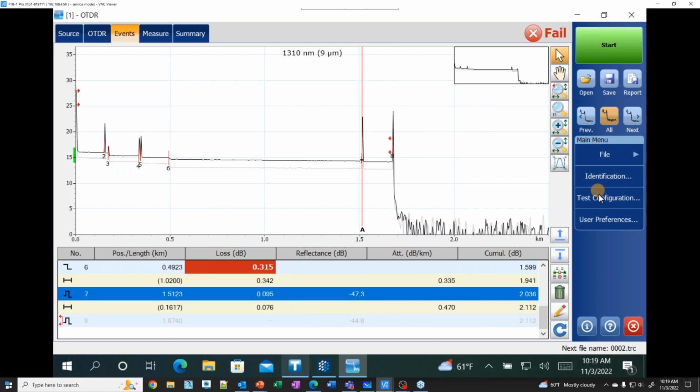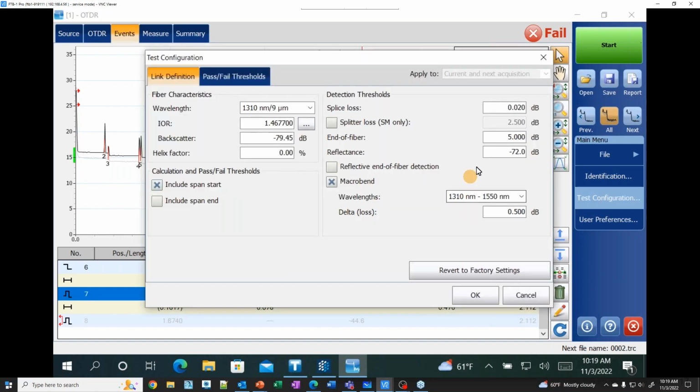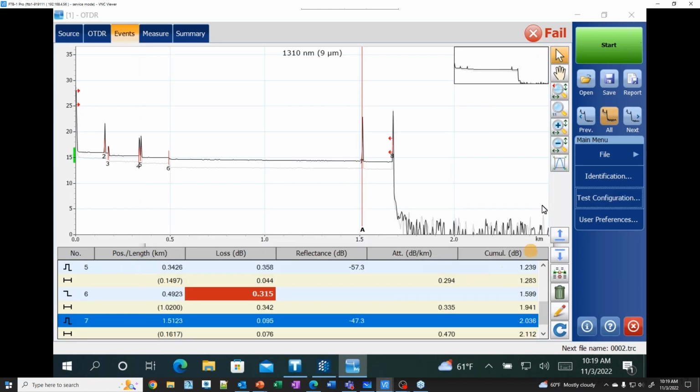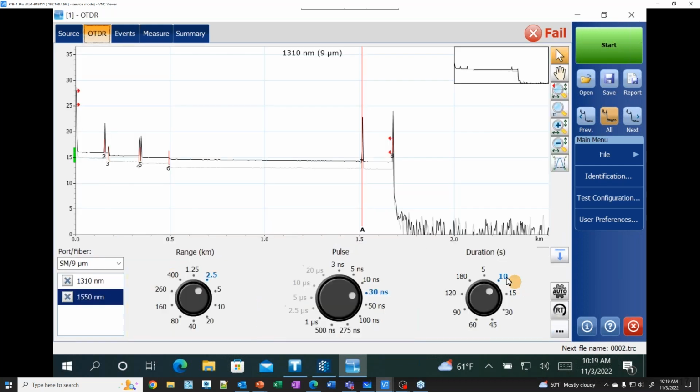So in this situation, I'm going to pinch it just to show. I like to show this, and if you've sat in my seminars, you've probably seen me do this before, just to show you how important it is to manage your fibers. So I'm going to grab a connection here. I got a connector here, just a UPC connector. I'm going to put a pretty decent pinch in there. I know it's kind of hard to see. And then I'm going to retest it. I'll do a quick test at, say, 10 seconds here.